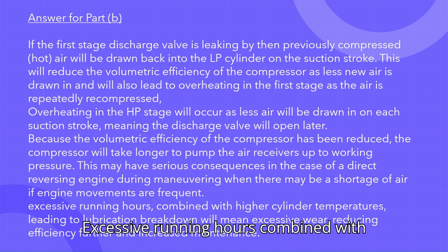Excessive running hours, combined with higher cylinder temperatures, leading to lubrication breakdown, will mean excessive wear, reducing efficiency further and increased maintenance.